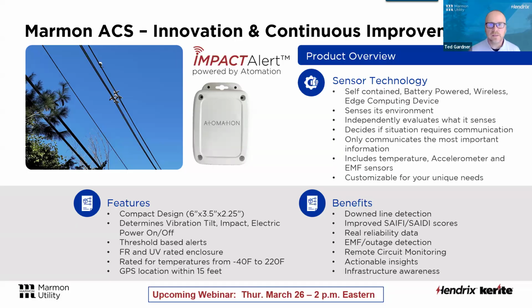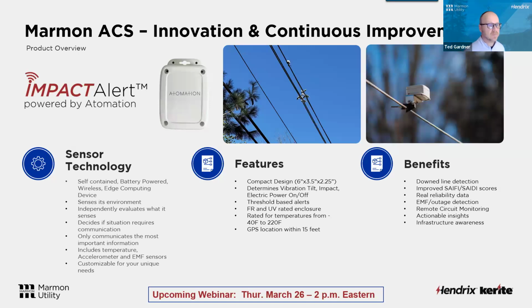But more than anything, we want to make sure that if there is some kind of an incident, somebody goes out relatively soon afterwards and takes a look at it. We don't want trees sitting on a spacer cable system or a tree wire system for that matter for very long because it's not fully insulated. So it'll eventually work its way through that covering. Now, it could be a month, it could be 6 months, it could be a year, but we don't want to cause any damage to the covering. So we want to clear those trees off there as soon as possible.